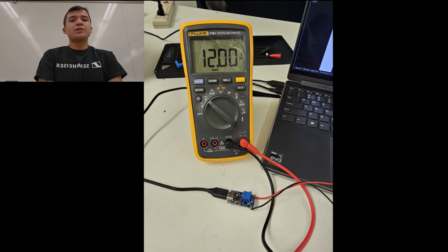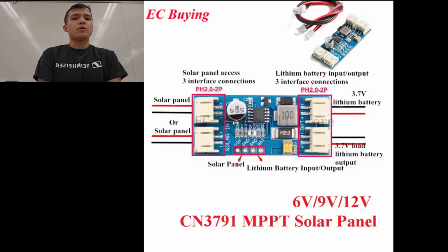For testing the power generation and storage subsystem, I started by setting up the buck boost converter, which takes input from the charging block and steps up the input voltage to 12 volts. The load/charge controller is rated for 12 volts or less, so having the maximum input voltage flowing into the controller will reduce charging time when the system is being charged by wall power.